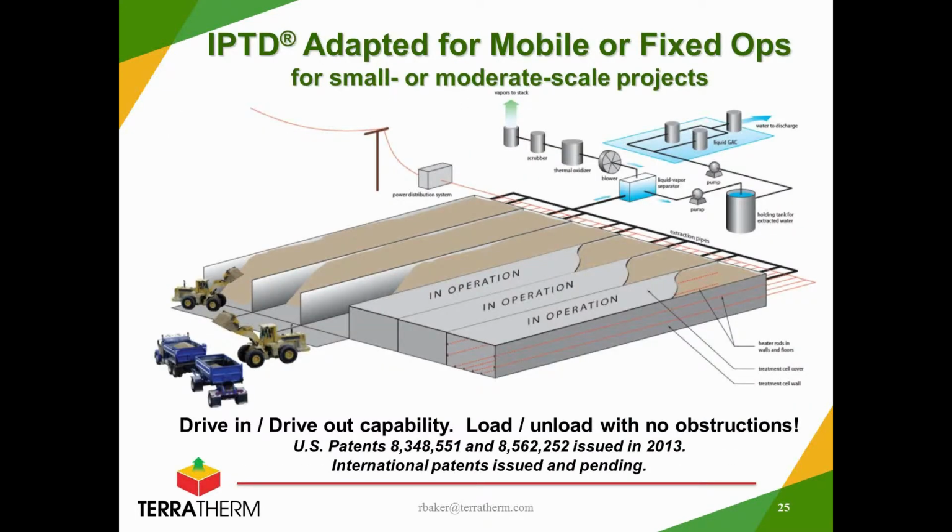I'd also like to introduce a different approach for treating smaller volumes. Obviously, the Da Nang project is very large, but there's many sites with between, say, 2,000 and 10,000 tons of POPs-contaminated soil that could be more cost-effectively treated in a series of chambers, as shown here.